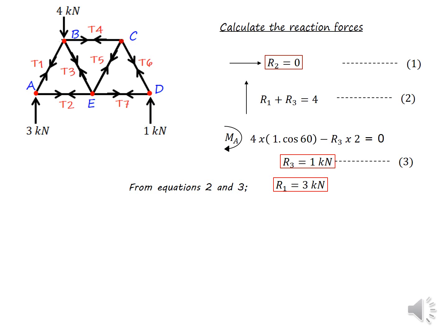Now, before moving to the joints, you can see in the figure that all the member forces I marked as tensile forces. The reason, hope you know, is that if you remember the sign convention we used in our previous lectures, we consider tensile force as positive, compression forces as negative.